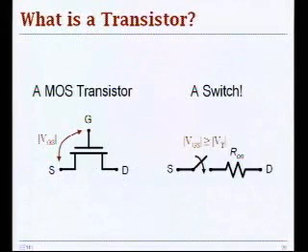So the simplest model of a MOS transistor is a switch. You can treat your transistor simply as a voltage controlled switch. If you have, for example, NMOS here, when your gate to source voltage exceeds a certain value that we call threshold, then your switch is closed, and your transistor behaves as an equivalent resistance between source and drain, between the conductive electrodes of your device.